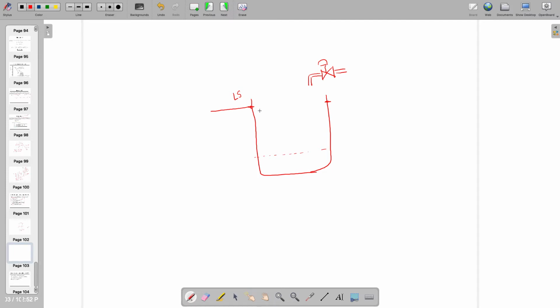Whenever this point is touched here, this will become 1, and it will tell my valve to shut, and it will close this connection, right? How to control the behavior? Generally, we are not doing only this, we are adding some controller also. That controller might be a P, PI, or PID controller. So which control are you going to use now?